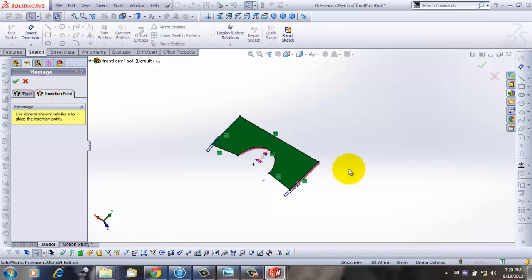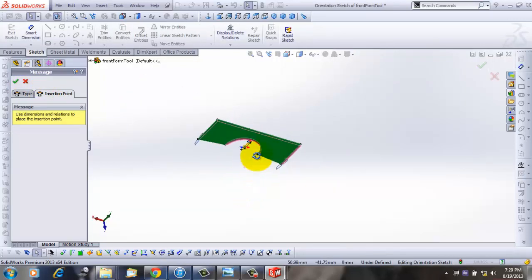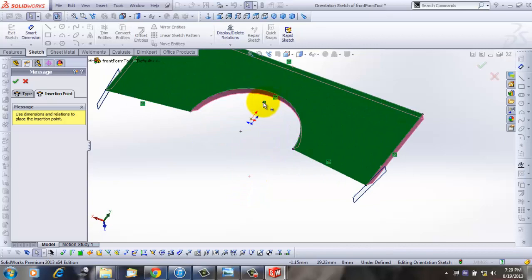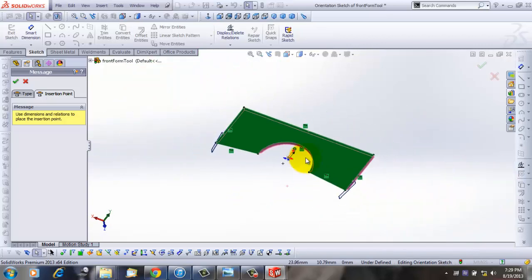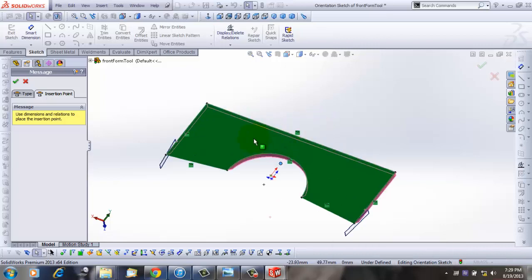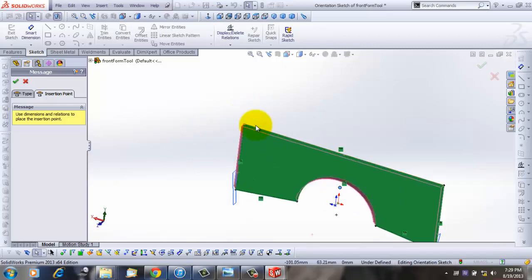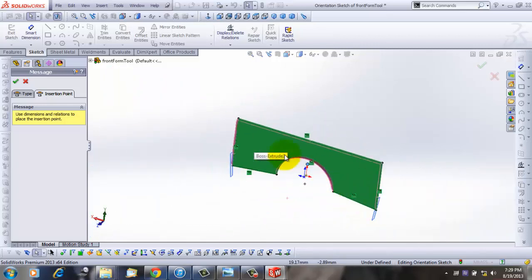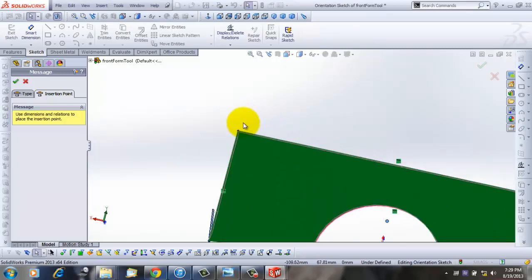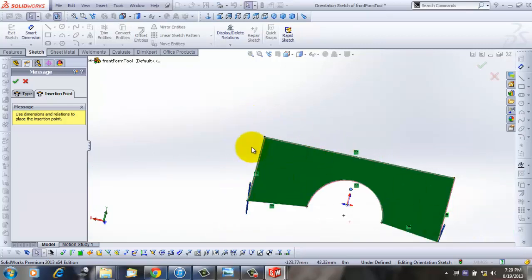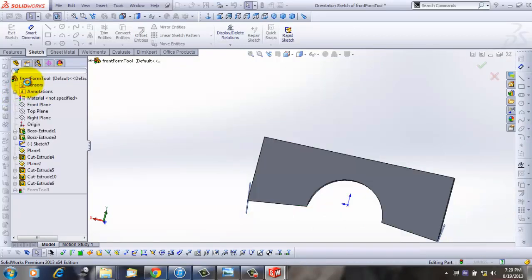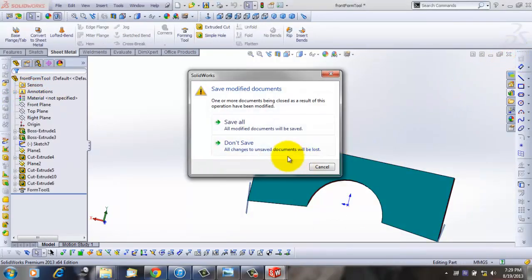Now, if you want to see one, okay, fine, I will go just after this. This is an insertion point which is newly added into SolidWorks 2013, where you can define a point which will be useful in locating or positioning your tool on the surface of the sheet metal. This wasn't there in 2012. They've included it and it's quite handy. You can keep it at the exact position, and since you can change it here, the referencing becomes much easier.